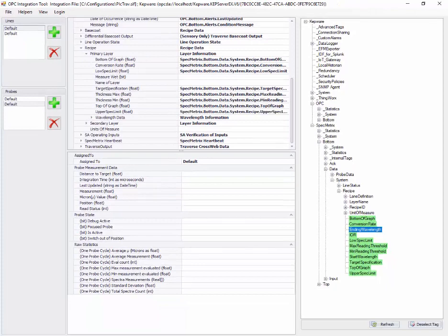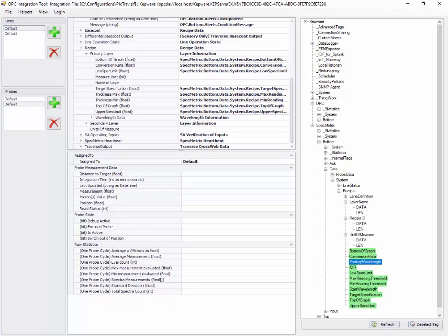When we're looking at Allen Bradley specifically, and there could be others, when it comes to creating a string, it is made up of two parts: the physical characters that make up the string and the length of that string. This is the same for Siemens as well, but it carries a little bit different mapping structure. In this case, Allen Bradley has a specific map for the data that we would actually grab the data and pull that data information up into the tag.